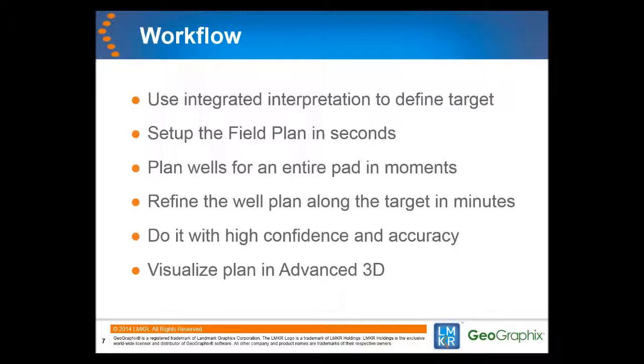Next, a field plan from multiple plans will be created in Field Planner. Multiple well sticks for each pad will be created in Field Planner based upon distance between wells, step-out distance, lateral length, kickoff depth, and reservoir target.